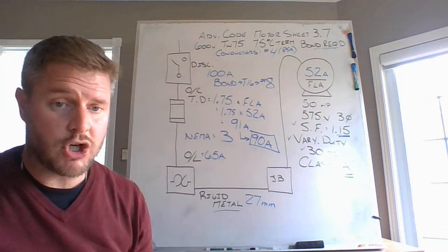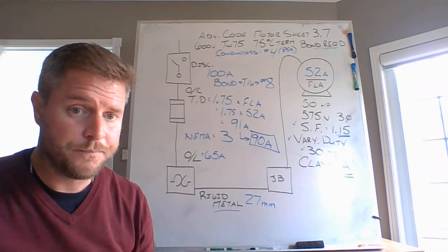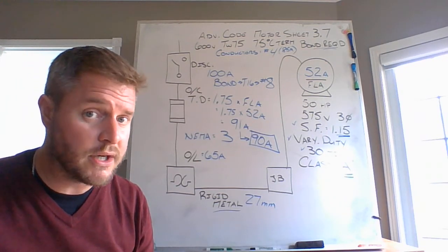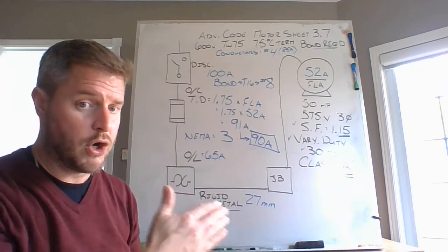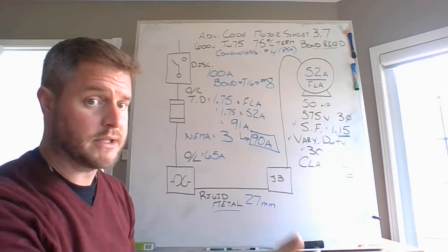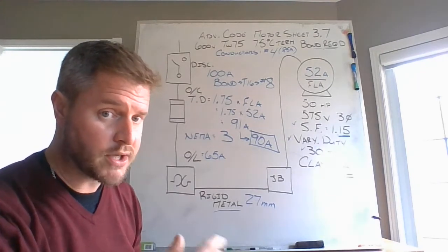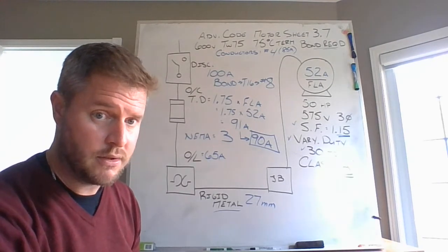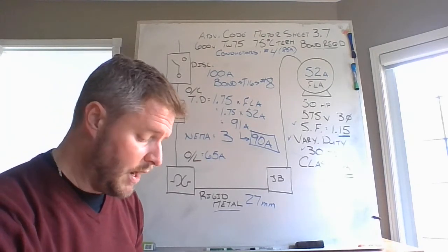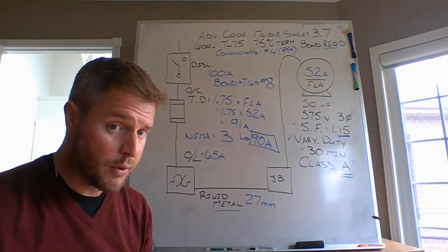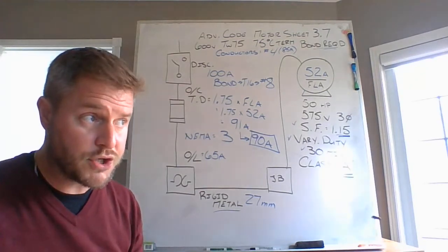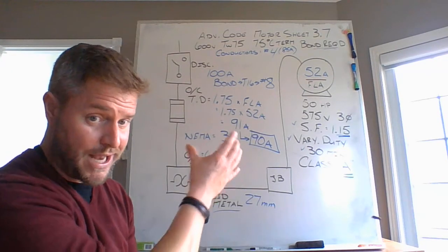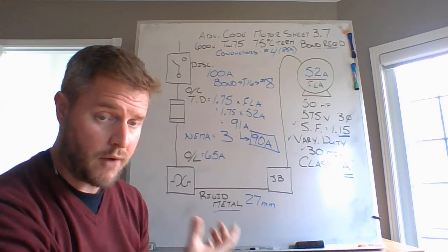So from that junction box going to that motor, those conductors are going to be 1.2 meters long. That determines where your junction box is going to be in relativity to your motor. And those conductors have to be 1.2 meters. Okay? Depending upon the horsepower rating of the motor, you have to be under 100 horse, which is our situation right now. We're at 50 horsepower.